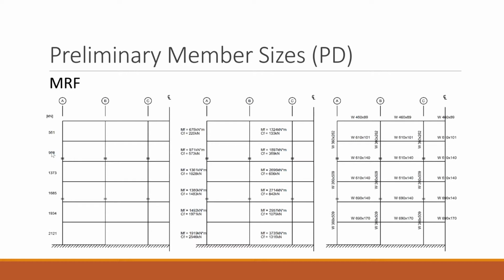In the MRF design, the weak beam strong column approach was used. Beams yield first, forming plastic hinges located 500 mm away from the column face. The plastic section modulus was reduced by 35% at the reduced beam section, and the beam probable moment acting on the column was calculated. Considering all the load effects, beam and column sizes were selected and shown in the right figure.